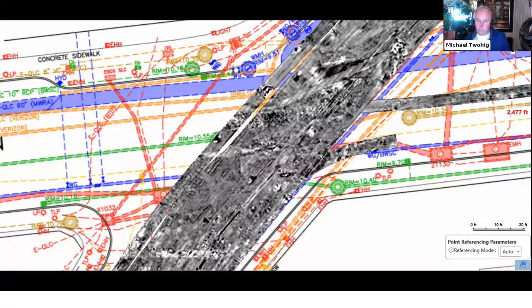The other thing it gives us is when we run through these streets, if we ever make a mistake surveying up a surface structure, because the GPR system, your software Examiner, gives us a position when we pick that data, we're able to do a QA/QC on our survey, whether it's a GPS or total station making a mistake. We get to see it because it'll show up as these bright reflections. So each of these road scars is something we investigate.